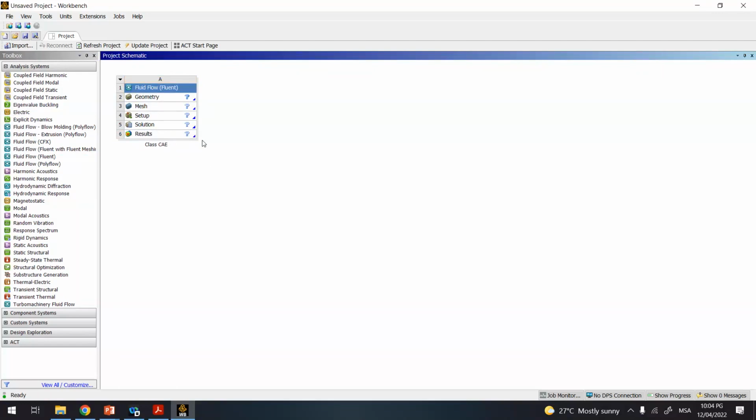Then, if we need to do several simulations, for example you have drawn one body, say I simulate a turbine, and then I want to analyze again using the same turbine. You can take this template and place it beside it. For example, right click and duplicate.